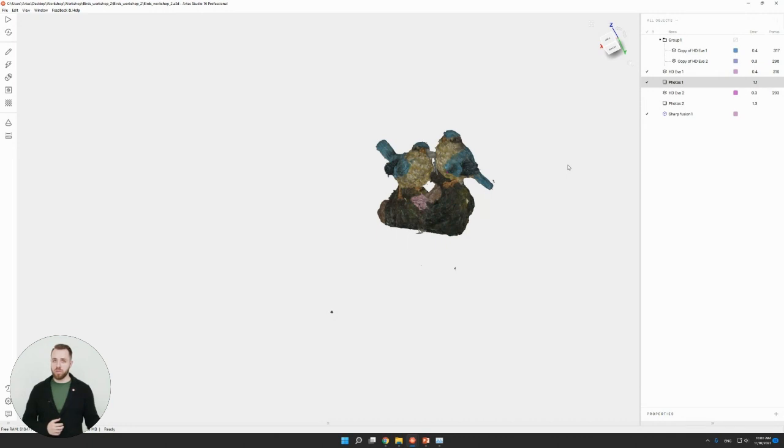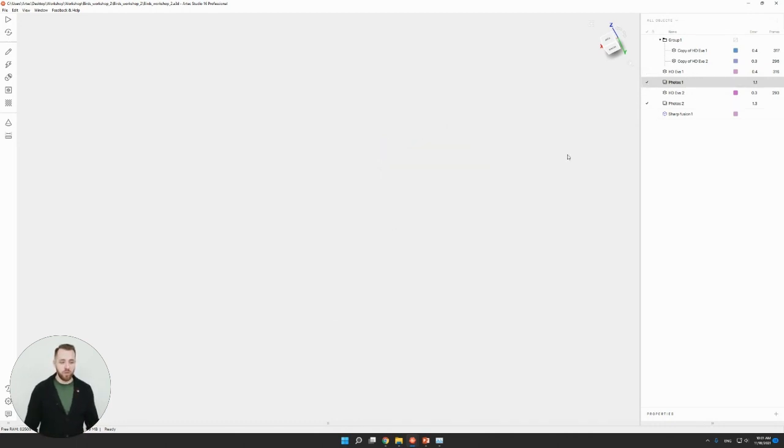And I run photo registration for this set of items. Once it's done, I move on to the second scan, to the second photo folder and to the same fusion, and run another photo registration. And when texturing the model, I select both of these photo elements in the workspace for texturing.